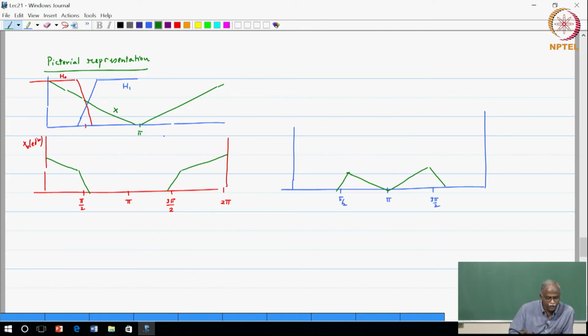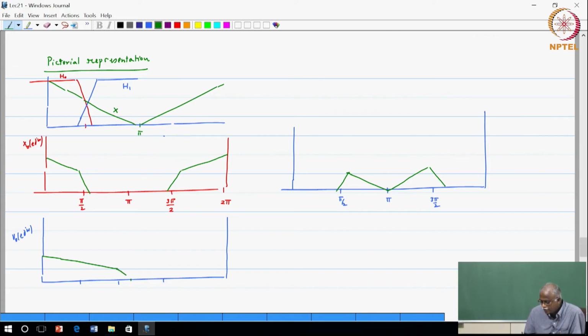So, the first step is the downsampling of x naught. x naught downsampled, we labeled it as V naught, V naught e of j omega. Please sketch that. V naught e of j omega, first of all, says that there is a scale factor of 1/2. So, we have to take that into account. Basically the signal will go down in terms of spectrum and it will get stretched all the way to pi. So, it is something of this type. It is down and then stretched.